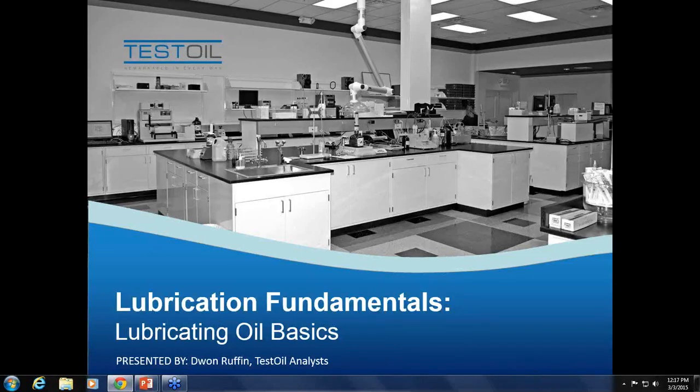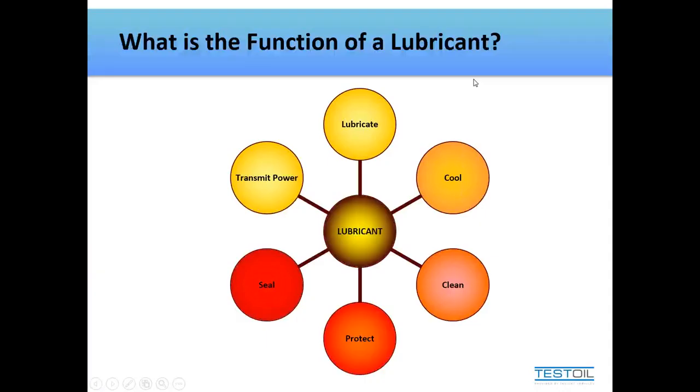All right, first off, what is the function of a lubricant? These six things here are pretty much everything that your lubricant does. It lubricates, it cools, cleans, protects, seals, and transmits power.